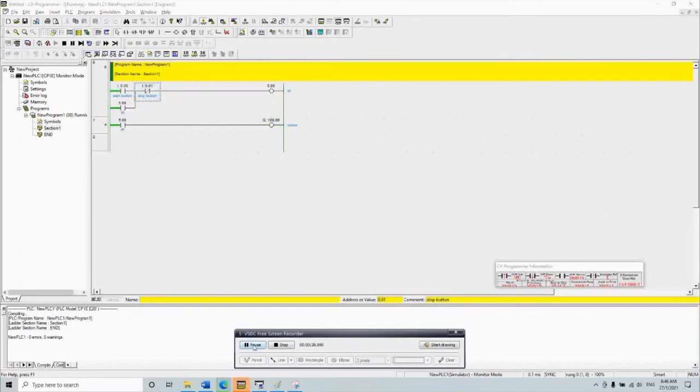We can see that the program's output will turn on when the start button is pressed, and will stay on when the start button is released, all due to the latching, which makes the program maintain the conditions so that the motor is still running. The program's output will turn off when the stop button is pressed and interrupts.